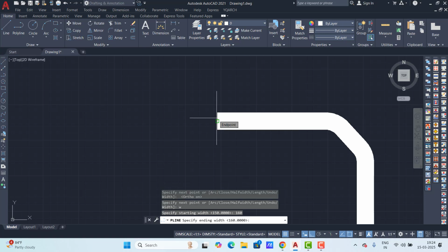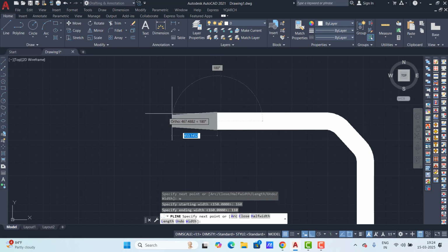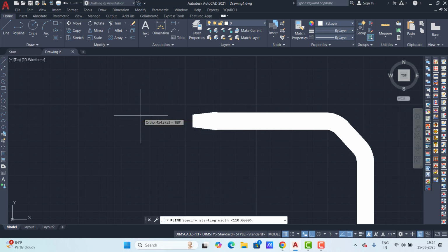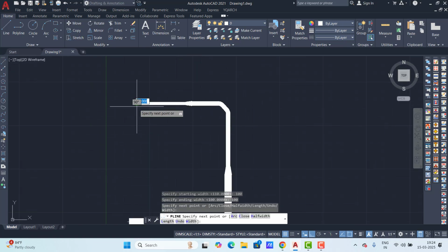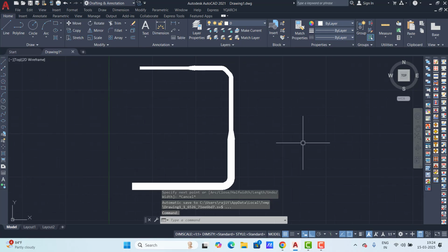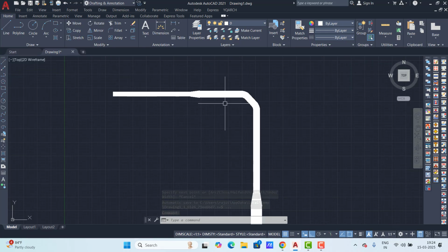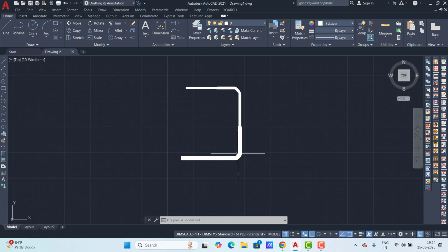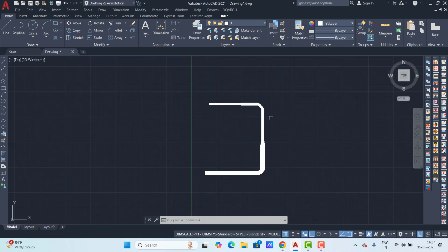Okay, that means if you have this type of line, and again one line is made here, this type I'm making. I want to create an arc here. So use this option, start center angle. So you give start here on this side, center here, and angle. If you know the angle you can type it, otherwise manually click this.